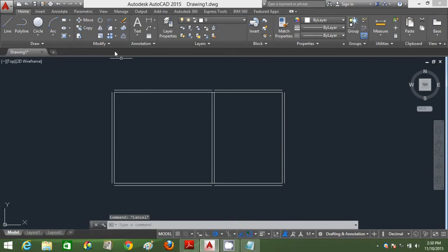And I'm going to use fillet now to join all the unjoined lines. Click fillet and click this line. Click the other line to join it. All right. So I'm just going to use the line command to extend this, in order to close that loop.